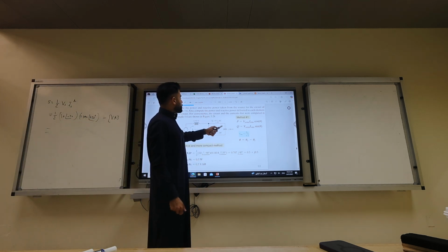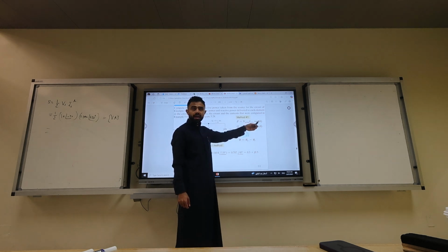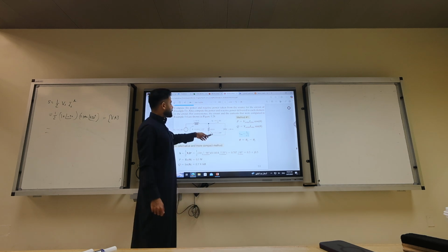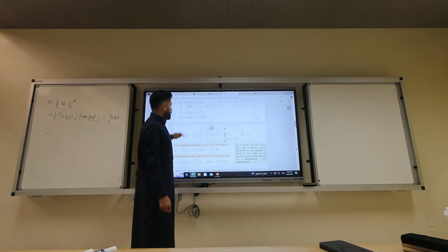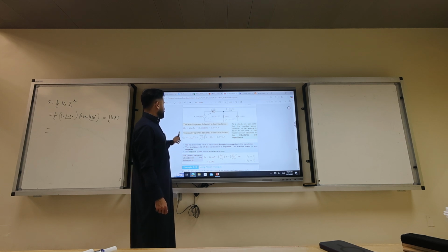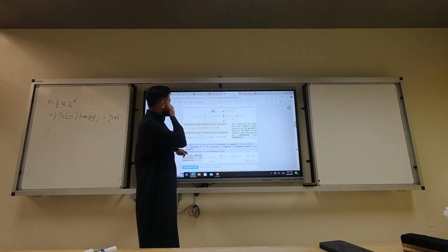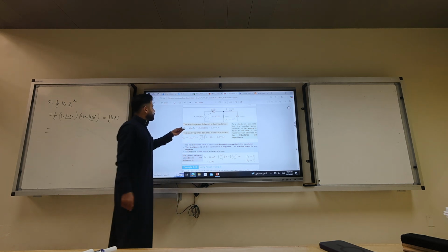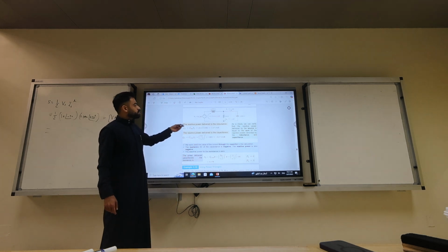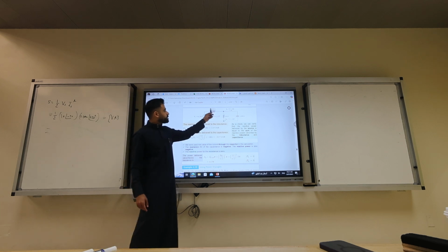Now, another method is you take the formula half V max I max cosine theta, or V RMS. For the reactive power delivered to the inductor, you can use the formula directly, which is I squared times X. X is 100.